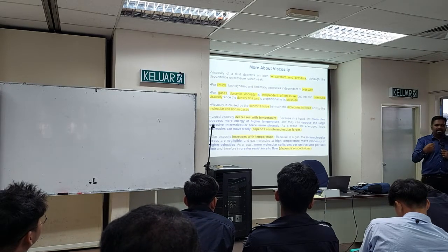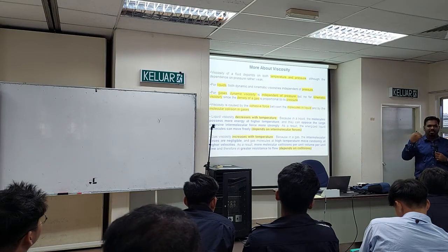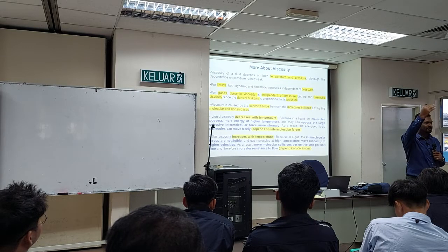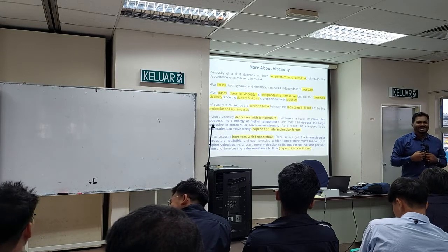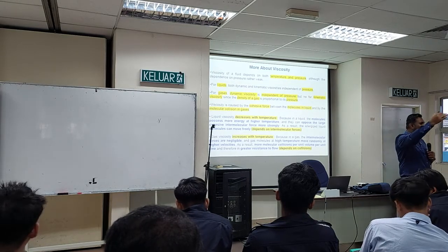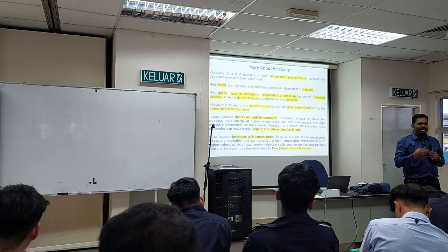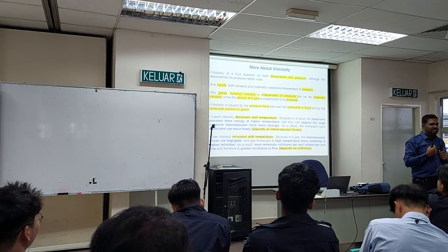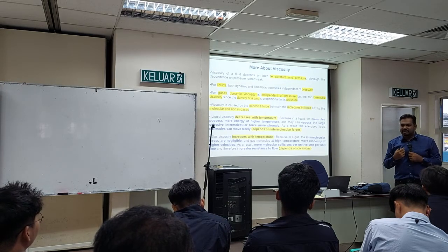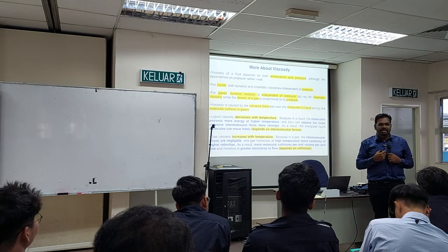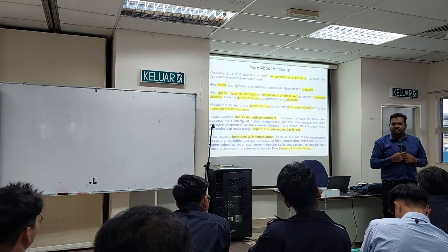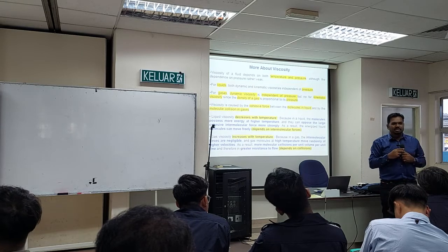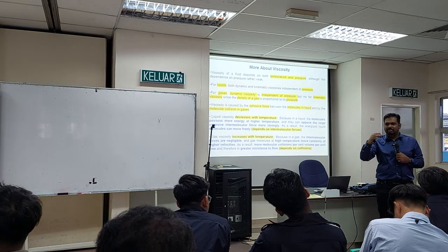So if you want to travel far, let's say you are going from Perlis to Johor, or from Perlis to Sabah. Not possible, right? Perlis to Johor is the maximum you can go. So 800 plus kilometers one way. Going and coming back, so 1600 kilometers. So usually how many kilometers do we change the engine oil? 20? So it depends on the fluid. But engine oil is usually at best 5000 km once.